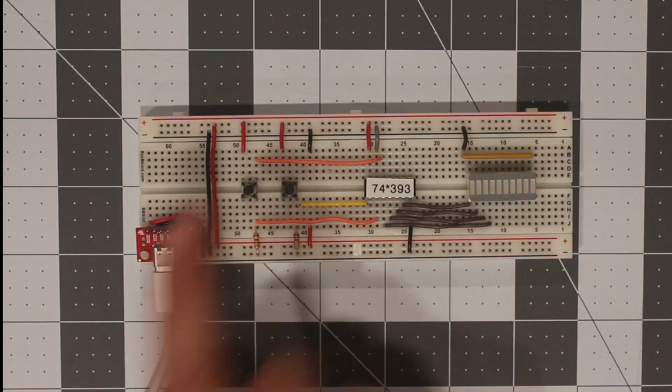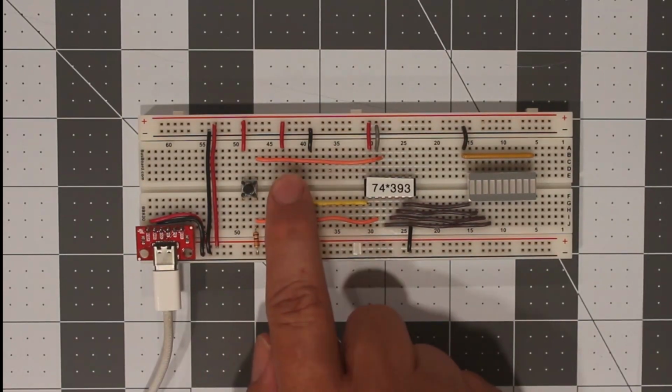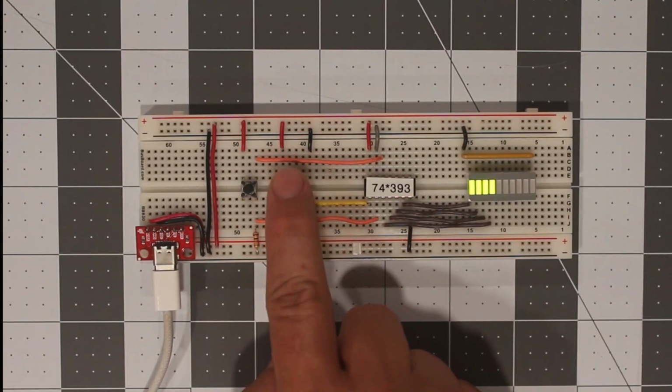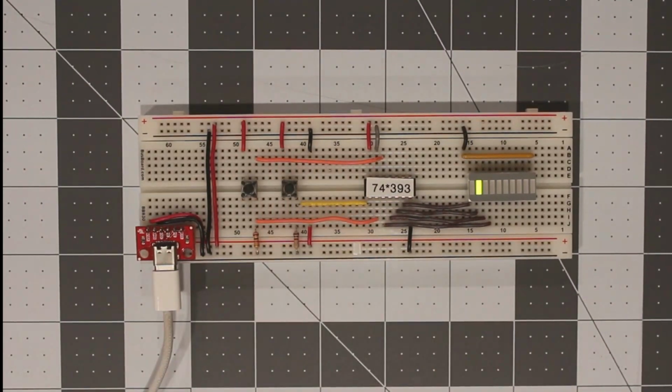For our test, we will reset the counter and begin by pushing the button 15 times. Our expectation was that 15 key presses would advance the counter 15 times, and we would see 4 bits enabled on our counter. However, as you can see, the counter has rolled over and produced 5 undesired triggers.